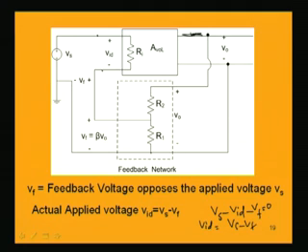That means the voltage at this point, Vf, which is the feedback voltage available because of the feedback resistance R1 and R2 loop, is negatively adding to the input or supply voltage Vs. The voltage available at the input terminals of the OpAmp is now Vs minus Vf.